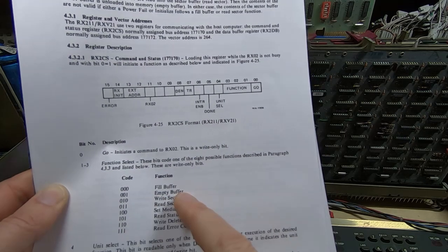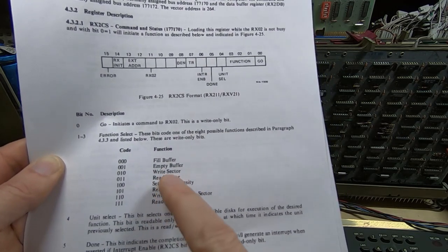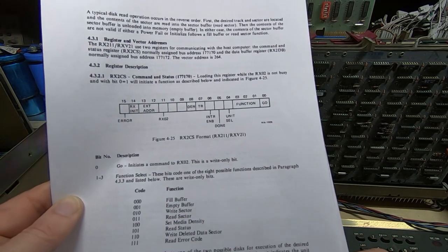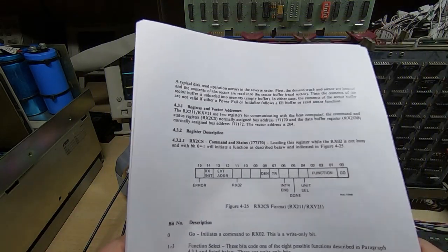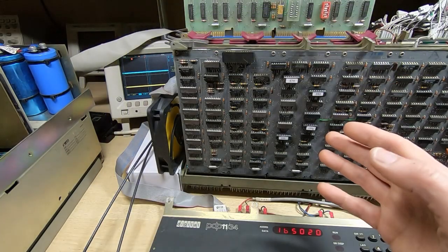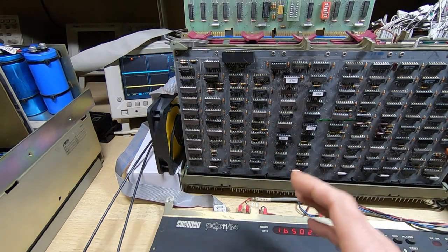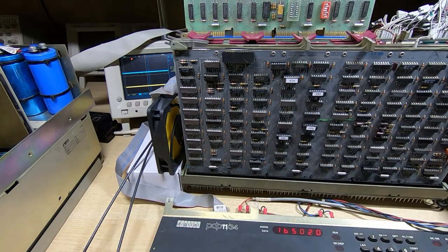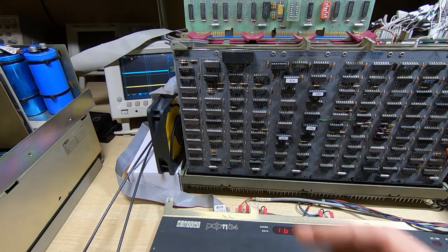And you can manually go through these functions, and that's what we're going to do. I'll do the first one here. In fact, we'll do a write sector because that's easy to see if it's working on the floppy drive, because we'll see the head move if it's working. What we're trying to do here is establish how much of the system, if any, is actually functional. Is it responding to commands? Is the interface doing anything at all? And will it accept commands, that sort of thing.